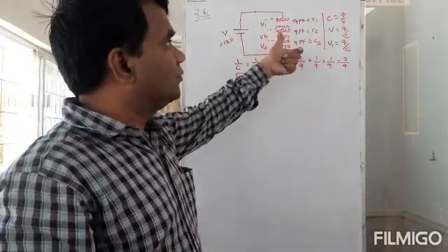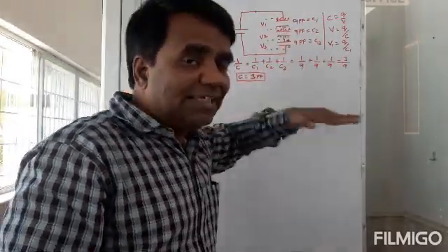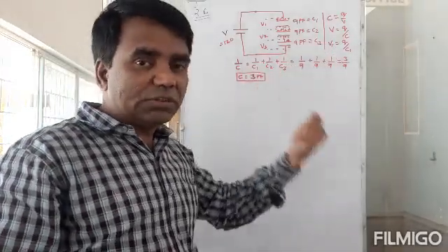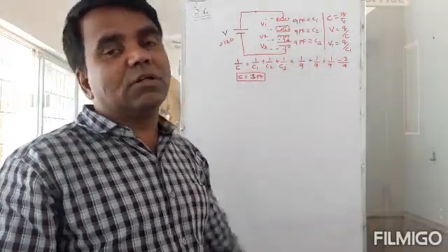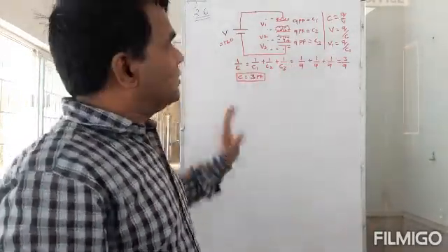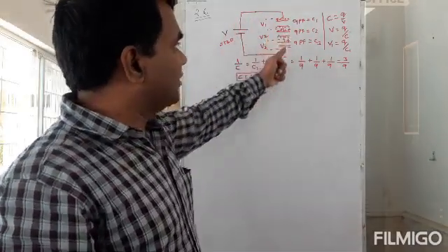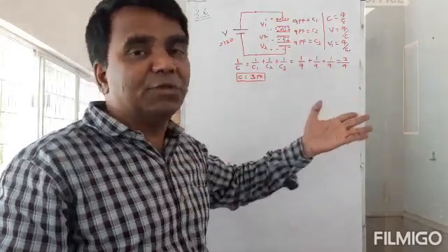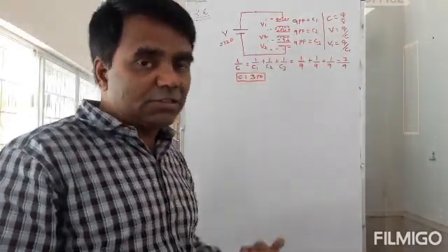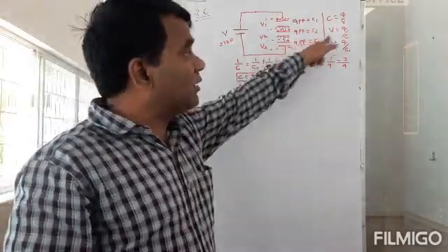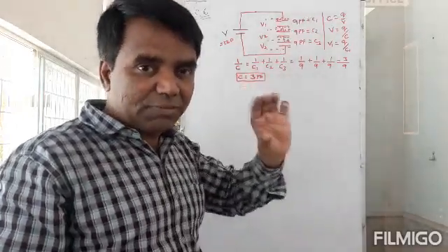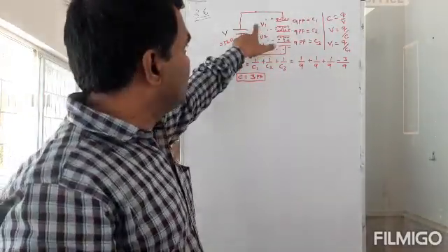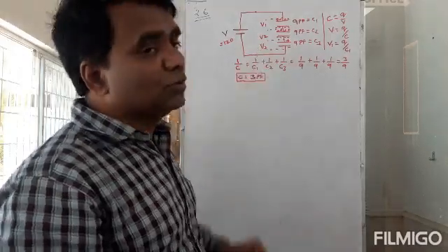This is V1, this is V2, this is V3. In this case, C1 is equal to C2 is equal to C3. Because you connected the capacitors in series, the charge on each capacitor is the same, and the capacitances are also the same. So the voltage across them must also be the same. So V1 must be equal to V2 must be equal to V3.